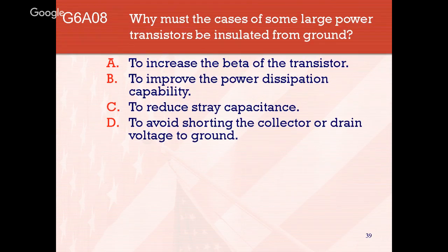Why must the cases of some large power transistors be insulated from ground? Mostly because your collector and your drain are exposed. You don't want to get those shorted against anything. So you want to avoid shorting the collector or drain voltage to ground.